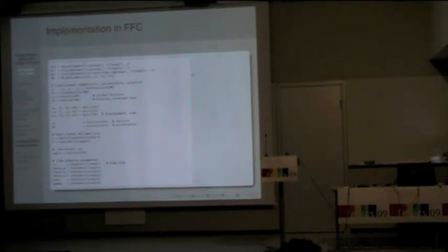What we do then is use a mixed element, and this is the definition of the trial function, and we use a split, this possibility to split to highlight the different contributions, which are the displacement, the temperature, the concentration, and the chemical potential, which is all we need to set up completely the model.